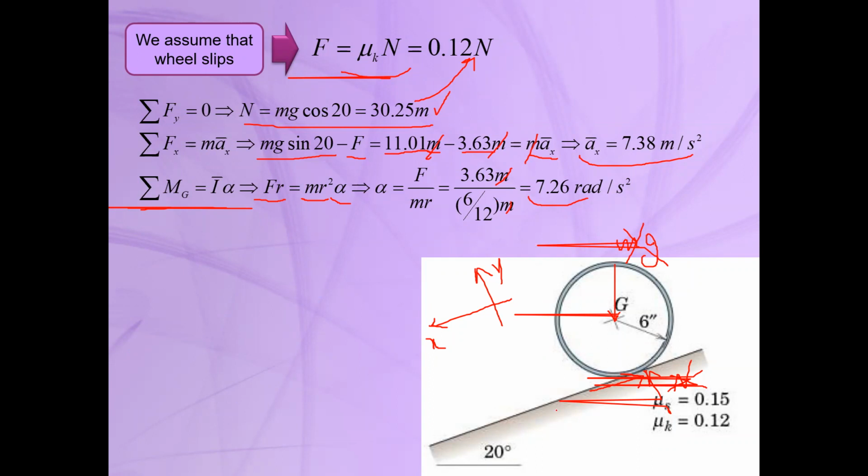And when you have slipping on the surface, it means your motion is a general plane motion, and you will have the kinetic friction force between the surface and wheel, and then you can calculate the linear acceleration and angular acceleration using these relations. Any question? Is it clear?